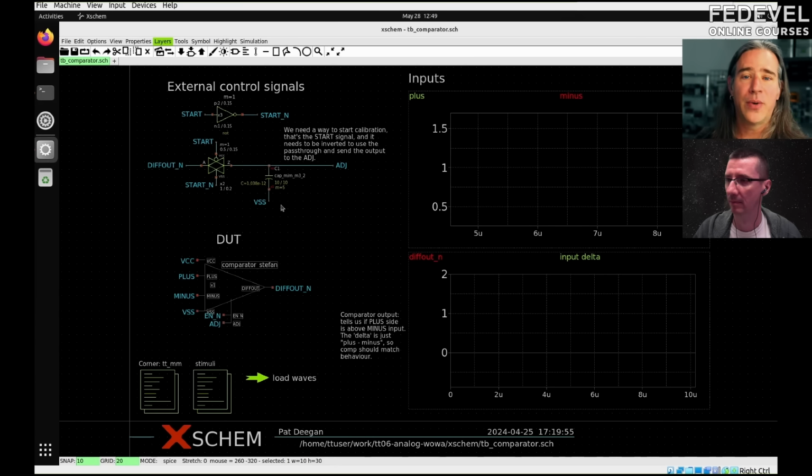Right. Now I create a test bench, and the question is, what is it that you want to look at? And the short version is, like everything here, it gets really deep. You have corners. The notion of the process has a standard deviation, right? So you can look at when the transistors are particularly fast, or when they're particularly slow, or when they're typical. And which one do you look at? Well, you could look at everything, but normally you look at what would hurt your system. So that's one aspect of it.